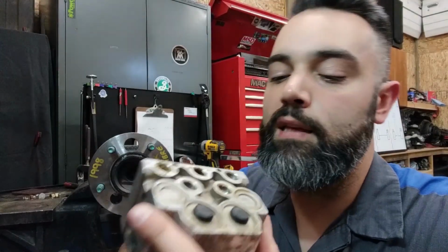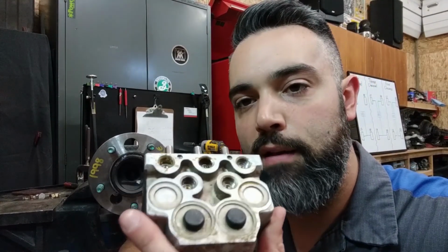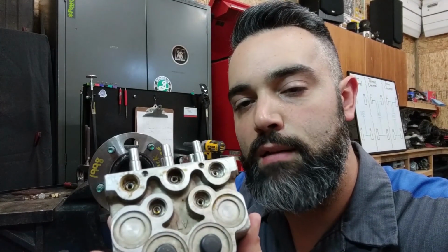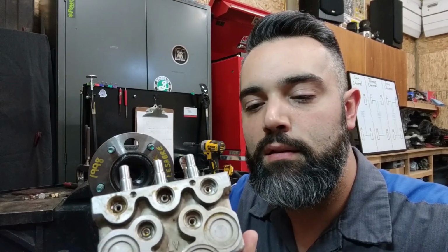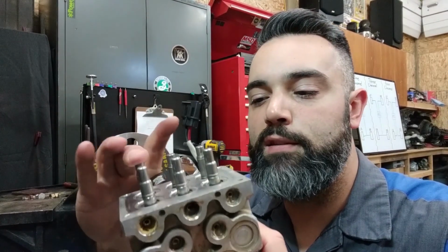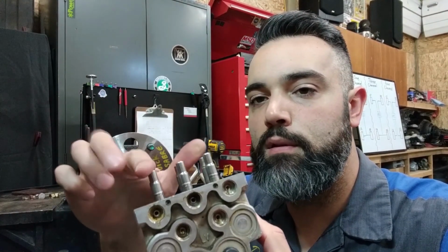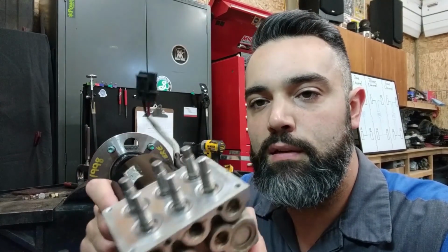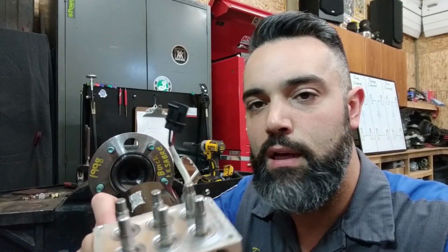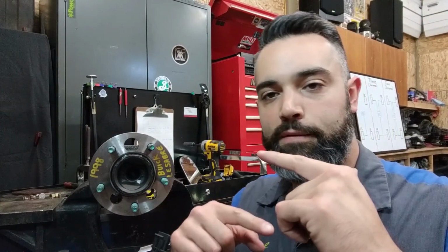On the bottom side of this, we find threaded fittings and sealing seats for the brake lines. This is going to operate these solenoid valves individually for each channel, and it's going to take that brake fluid pressure, block off the driver's input, so it's going to isolate it from the driver.